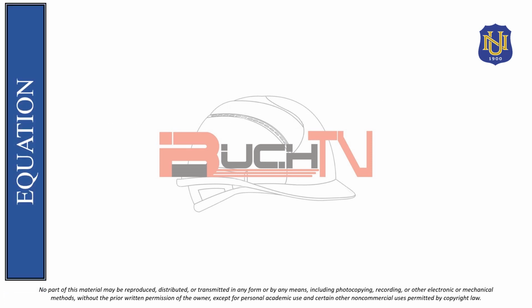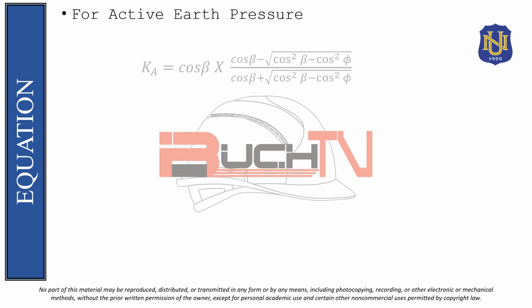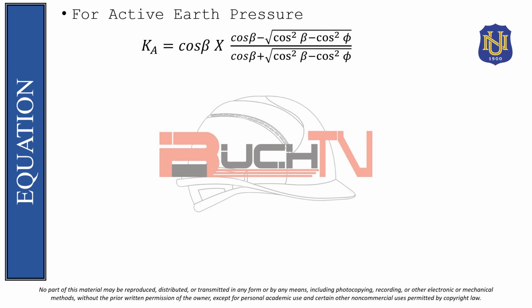For the equations we are going to use, for the active earth force or earth thrust on the wall, we should use the active earth coefficient equation for sloping backfill, which is K sub A is equal to cosine of beta times cosine of beta minus square root of cosine squared of beta minus cosine squared of phi, divided by cosine of beta plus square root of cosine squared of beta minus cosine squared of phi.